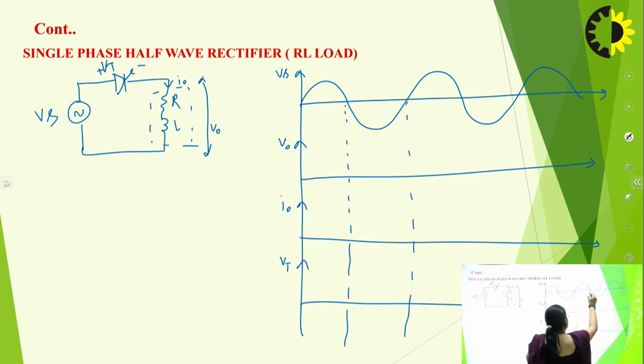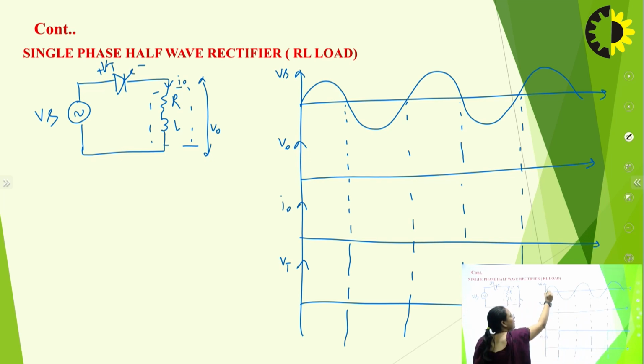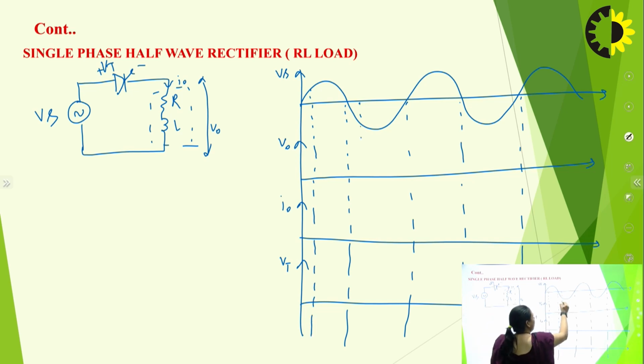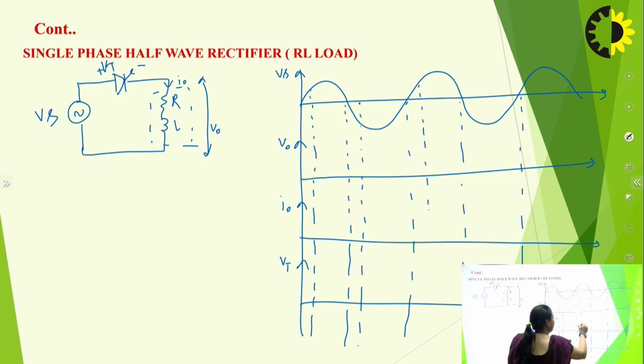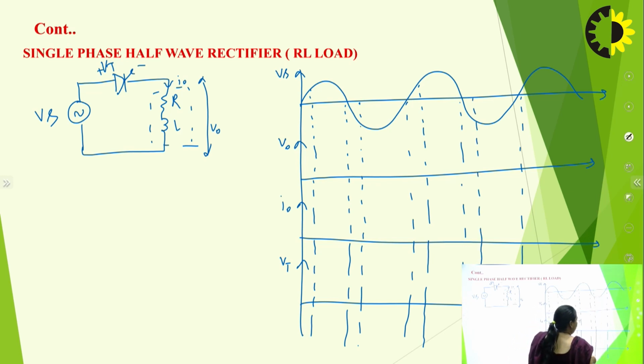So again here, during the positive half cycle of the supply, thyristor will be forward bias, and during the negative half cycle of the supply, thyristor will be reverse bias, right? So this is understood. Now thyristor will get triggered, meaning turn on, as soon as gate is getting the pulses, right? So you can see here, let's talk about the forward cycle. Let's start from the alpha.